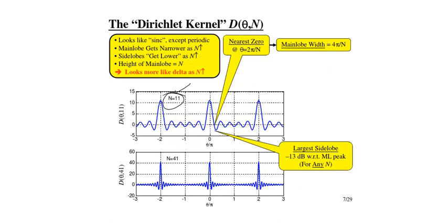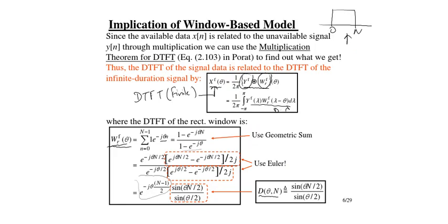When we append more and more samples in our signal of interest or a signal of process, what will happen? The main lobe will essentially be going down, right? When we go from finite to infinite, we get only an impulse, right? So that's what I just showed here. We get only an impulse when n is infinite.